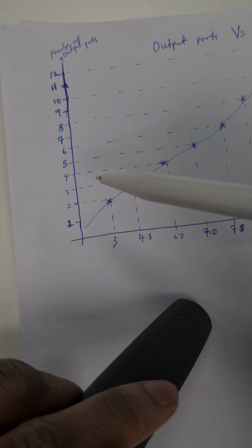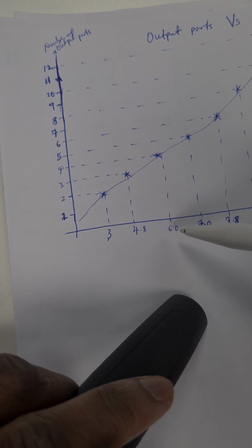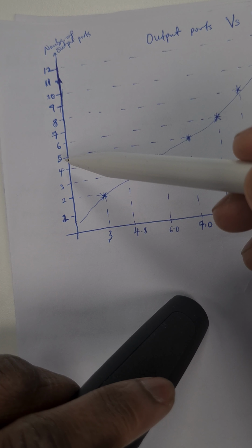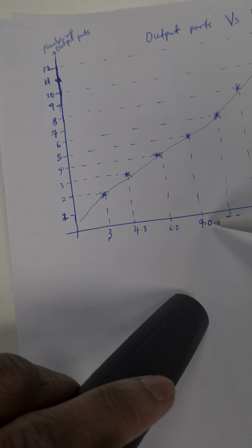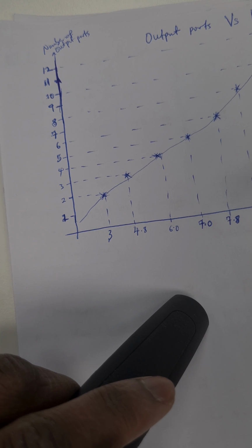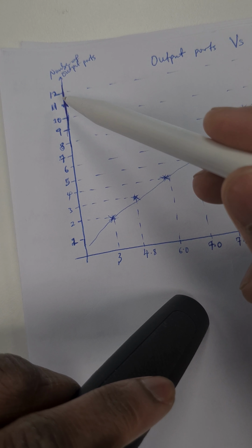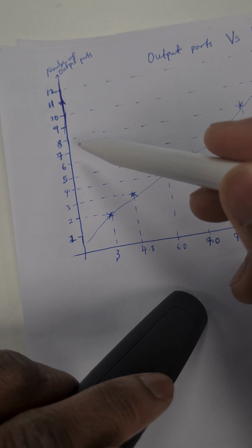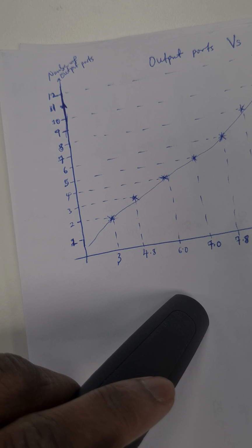In case you have 4 ports, you have a theoretical insertion loss of 6 dB, and when you have 5 output ports, you'll have about 7.0 dB insertion loss, and it goes on like that until 12. If you have 12 outputs, just like the case where we have 8 ports, we believe our insertion loss will be around this range.